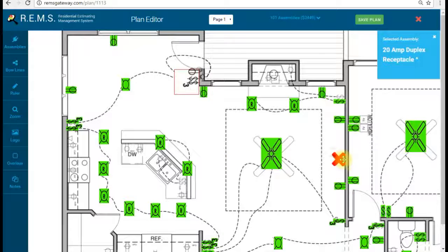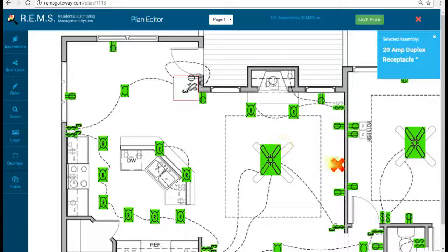So we can cross something out of their plan or white it out and say, no, that didn't happen. A lot of times I will use the cross because I want it to go back to their designers. And so their designers can see, okay, he's saying that we didn't place it right, and he showed with his new ones how he did it, and they can make their corrections. So the next time they send out that plan, hopefully it's repaired. It makes for more accurate estimating.